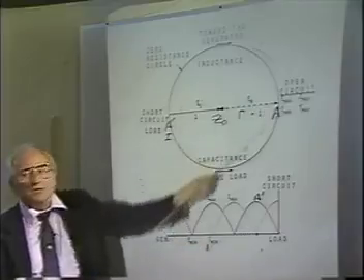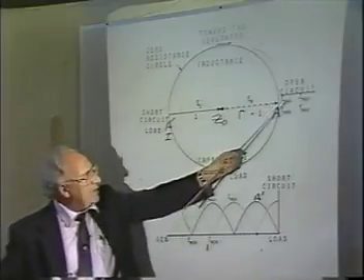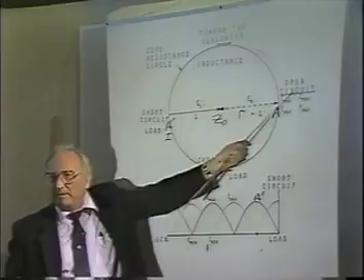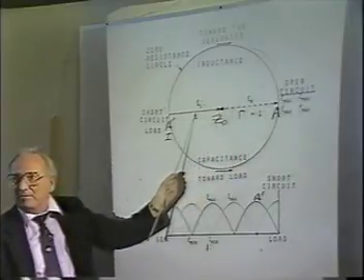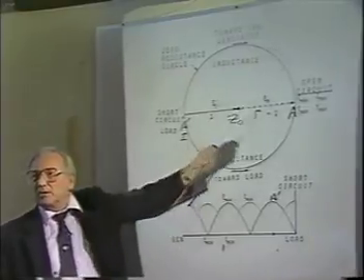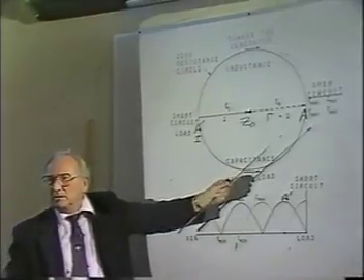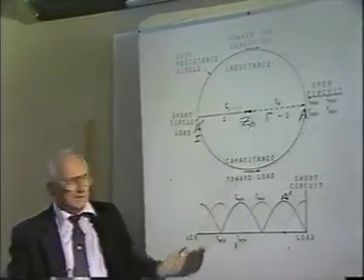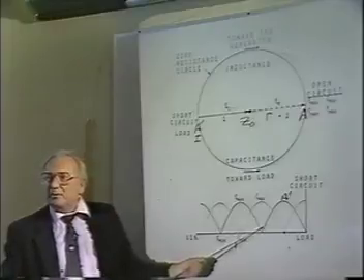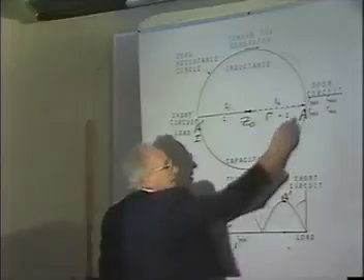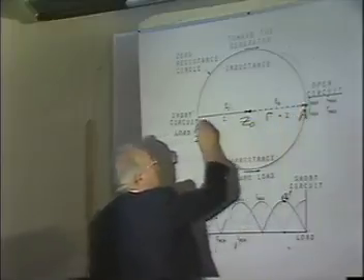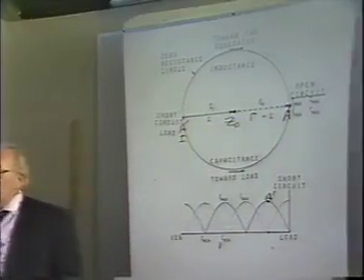That's what this chart is. This chart is a plot of this and this together, right? Because when voltage is minimum, what's the impedance? Minimum, right? But the current is something different, isn't it? It's 180 degrees away on this chart. On this transmission line, it's 90 degrees away. So the same point on the transmission line here is this point here, voltage-wise. It's this point here, current-wise.